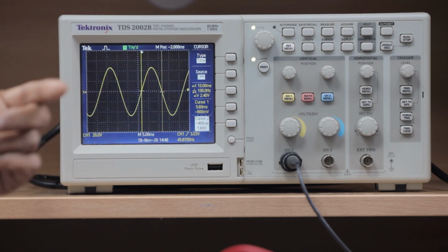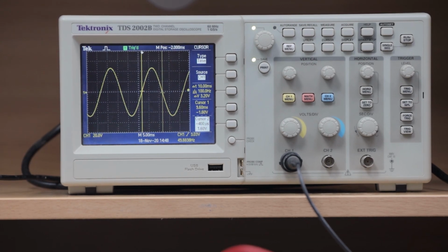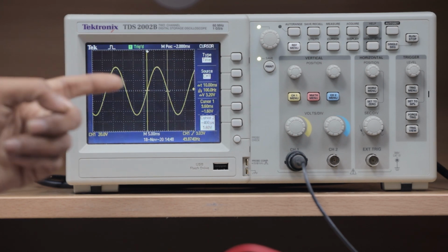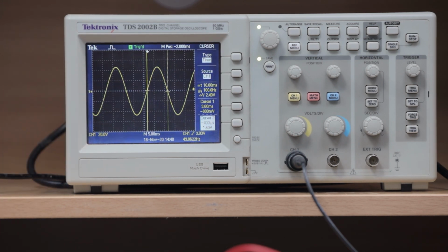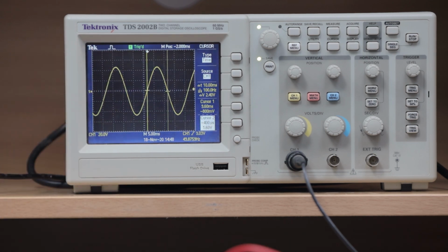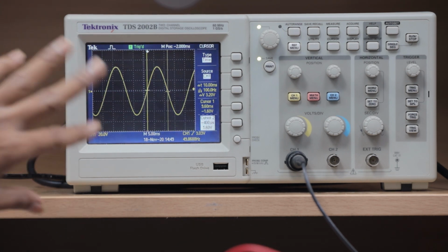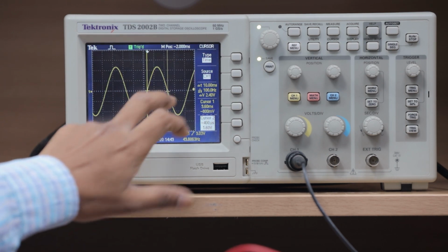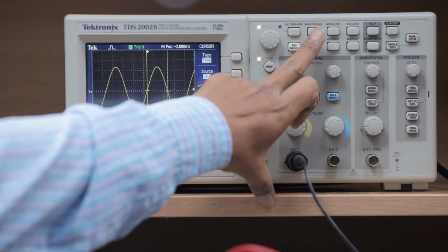This value divided by 2, that is 180 by 2, equals 90 degrees, and this value divided by 3 gives 120 degrees, that is 6.6 milliseconds. Like that we are converting the firing angle from angular position to time. Now, with firing angle 0, press the measurement button.